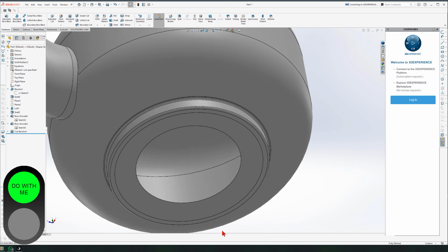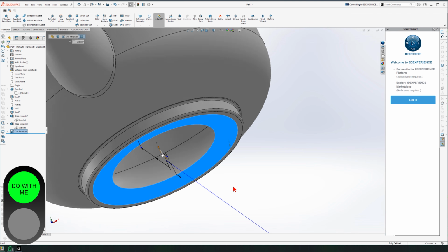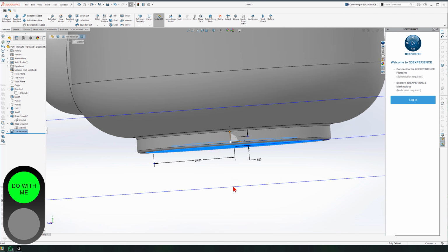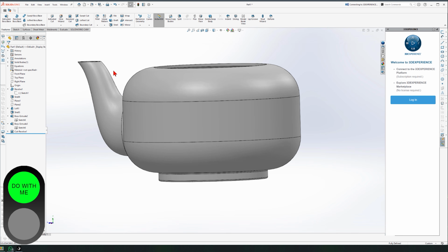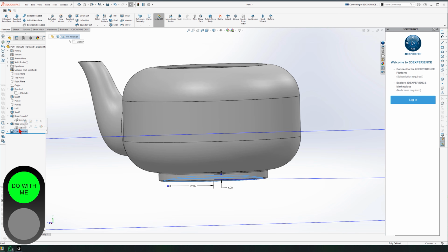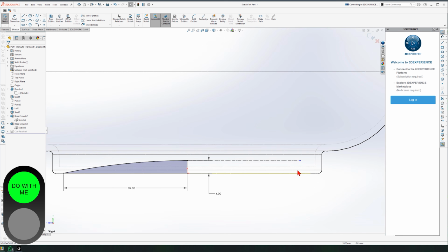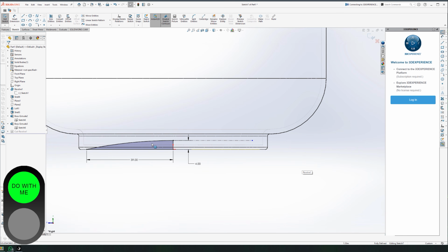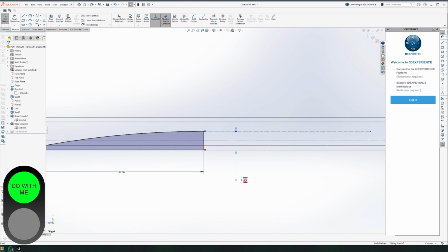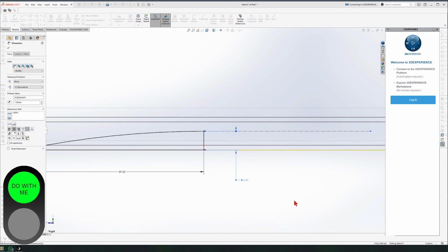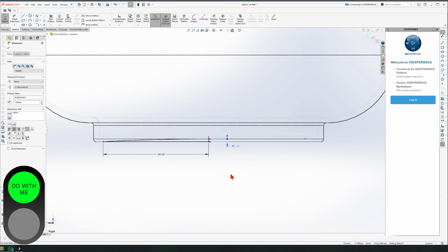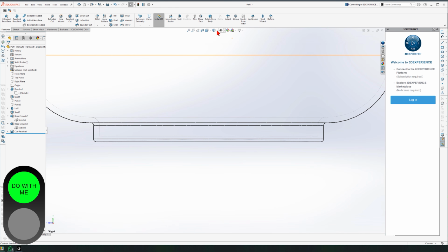So we create an opening, but this is too much. The height was too much, so we need to change that. Edit Sketch, change the view to dash lines. Oh, my dash line is all the way down here. 4 is of course too much. So let's change it to 1. Okay, change 4 to 1 and click OK.